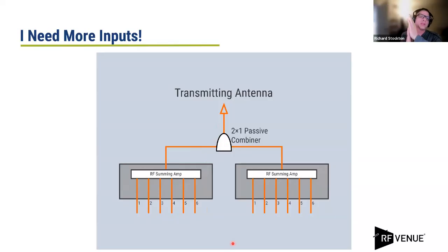Can I add something, Bob? Yeah. Okay, so when we show you this 2-to-1 passive combine, it works well with lower levels. So 10 milliwatts coming into each port on the combiner, or 50 max, because the isolation is good. But if you're going above 50, that's where more isolation is needed, and that becomes costly. There's ways to do it, but most of the time people don't go more than 50 anymore. It seems to be common.